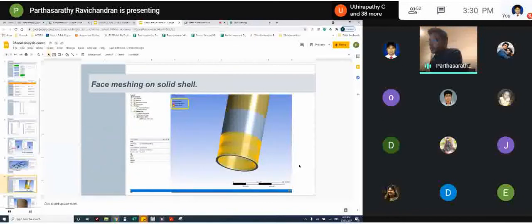So I tried to show you directly how a solid meshing would result. In this case, I tried to do a solid meshing on the bottom part only, and the face meshing came as a fail because face meshing was not suitable for a solid body component here. The bottom has a diameter of about 4 meters and a thickness of about 20 mm.